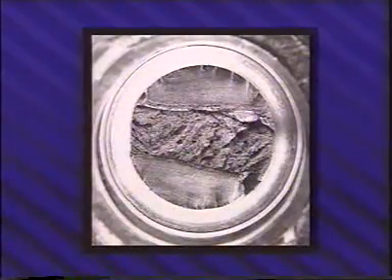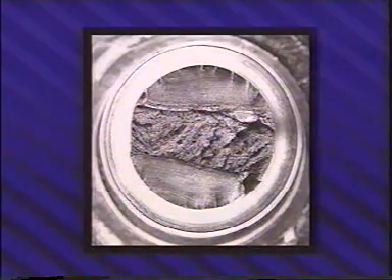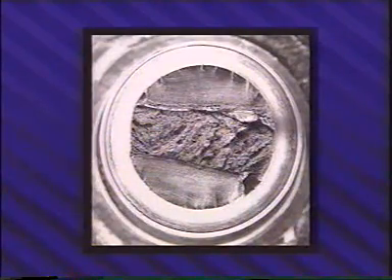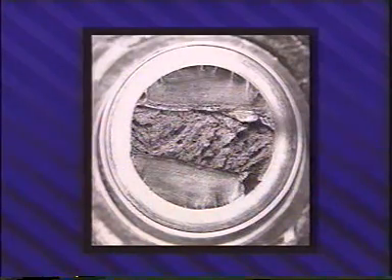With a reversed load, each crack is opened in one half cycle, closed and pressed together during the other half cycle. This open and close action rubs and polishes the high points on opposite sides of the fatigue crack. Under unidirectional load, the rubbing is less pronounced or non-existent. Consequently, striations and beach marks are usually more observable after alternating unidirectional loading than after reverse loading.